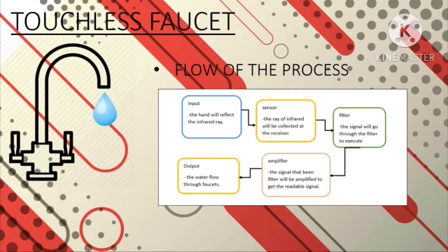In short, the band pass filter will selectively pass signals within a given frequency range and attenuate those outside of it, while the non-inverting op-amp circuit is expected to create an output signal that is greatly amplified and in phase with the input. When amplification and frequency selection are needed for signal conditioning applications, these behaviors are essential.